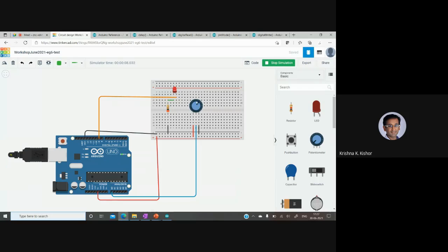So this is a variable resistor. Depending on the resistor value, the voltage that is coming out from here will change. That is being sensed by this embedded system as an input. Since it's an analog value, because it's a continuous range of values, that's why you're using the analog in. And depending on this input, I turn the voltage over here on the output side.